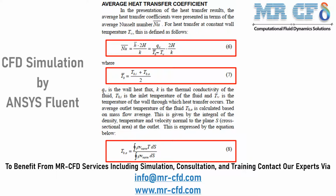Now, as was mentioned in previous slides, we had defined a report to calculate the average temperature on the outlet boundary, and we're going to use this temperature and our inlet temperature to calculate this average temperature. Then we're going to implement this average temperature in the Nusselt equation in order to calculate its value.